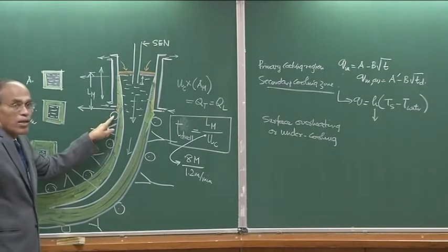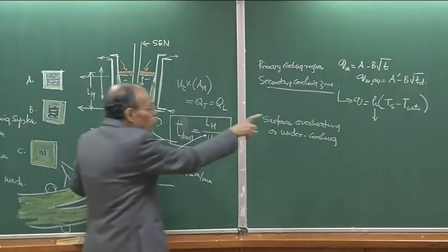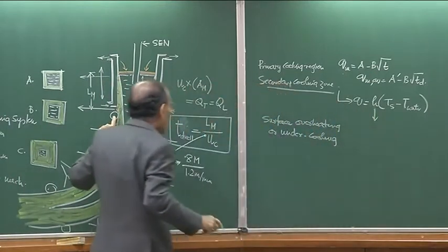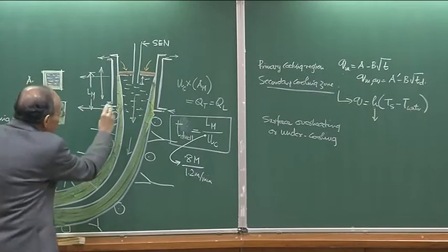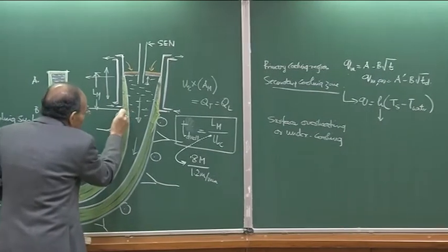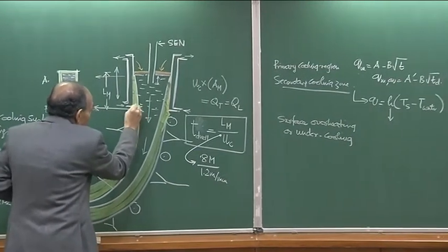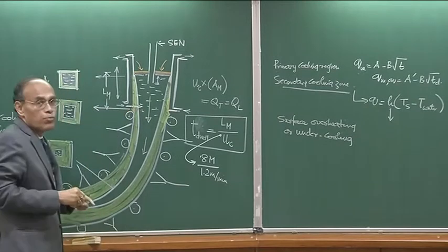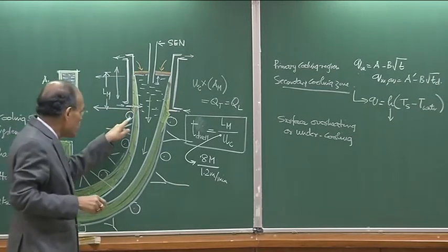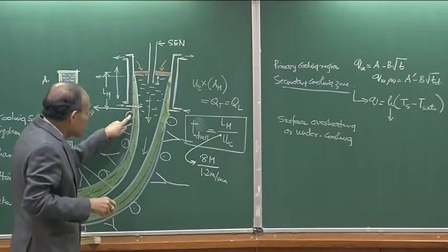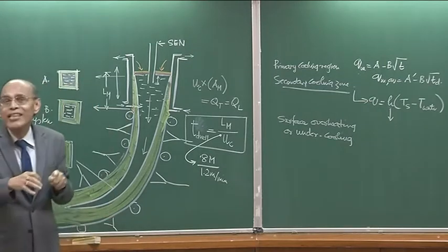These sprays provide a rate of heat transfer through an appropriate heat transfer coefficient, such that the heat flux value at the mold exit and the heat transfer rate offered by the first spray are not drastically different.